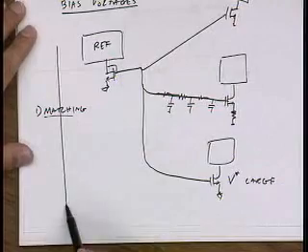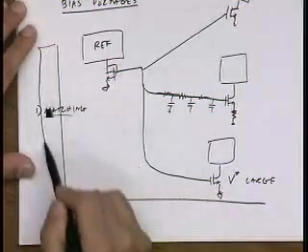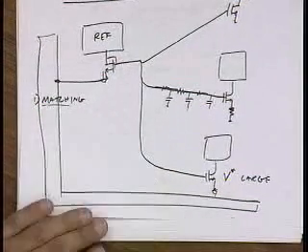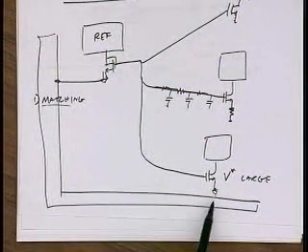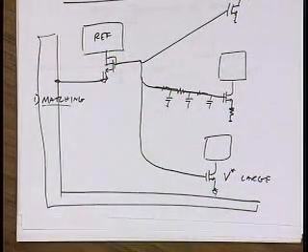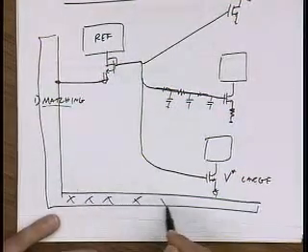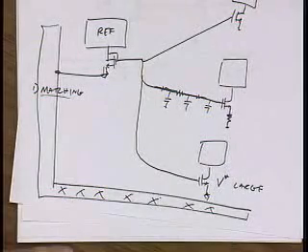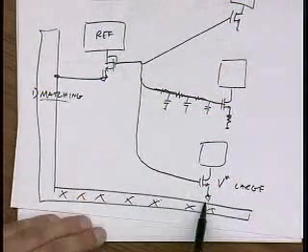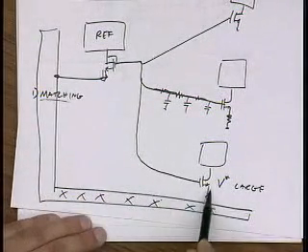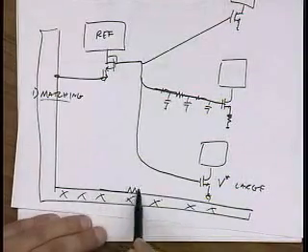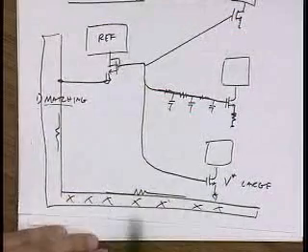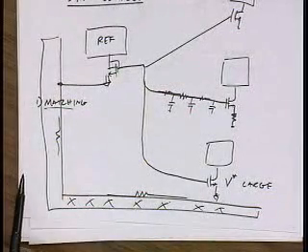So you might have this big bus going around, that's your ground, and then here this would be a local connection to ground, and you would say, okay, great, this is a low resistance path, I've strapped this with a lot of metal, and great, that's low resistance. But as Toda pointed out, because there's current flowing on this path, any kind of resistance here introduces a mismatch. So you do a really good job, you do a good layout, and there's very little resistance.